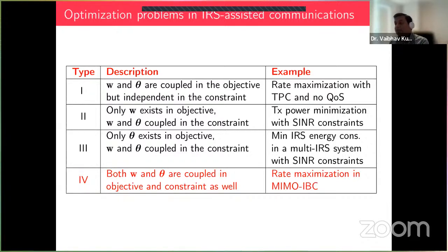Specifically, if you go into the millimeter waves, as we know, the propagation characteristic is not very good. The power loss is very high in those frequency bands, but we have a large chunk of spectrum that is unused there. So we can have broadband services there, and we will get very high capacity. The problem is that the propagation characteristic is not good, and we can put these IRSs in there to act as some sort of passive relays, or even, as people are talking about nowadays, active IRSs. So this is the motivation of using the IRS for next generation communication systems.